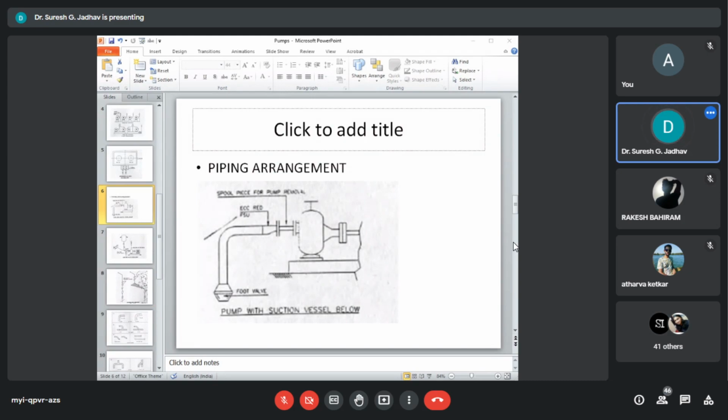Then we can go for the face side up or face side down for eccentric reducers. This line shall be drainable near the pumps. The suction is generally one or two sizes larger than the pump suction nozzle for centrifugal pumps. Now, the next requirement is the NPSH requirement.